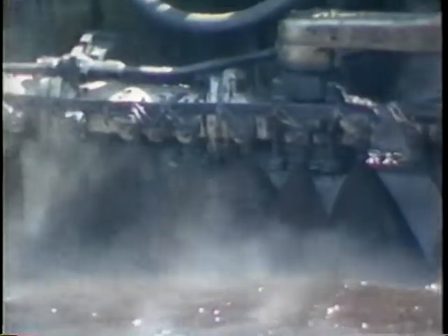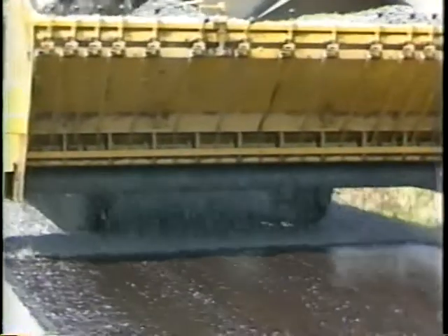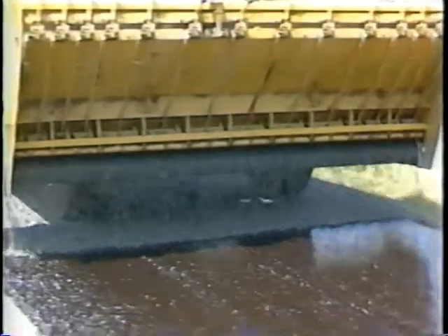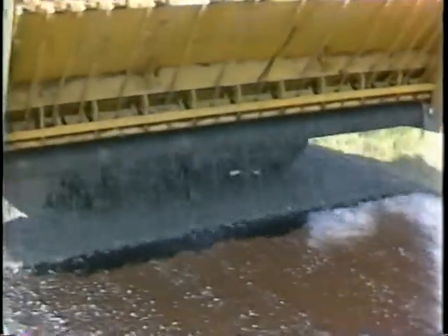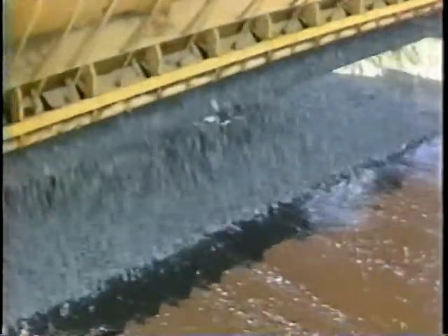Emulsified asphalt is recommended. However, cutbacks and asphalt cements can be used with good results. Select an emulsified asphalt based upon the compatibility of the emulsion and the aggregate.